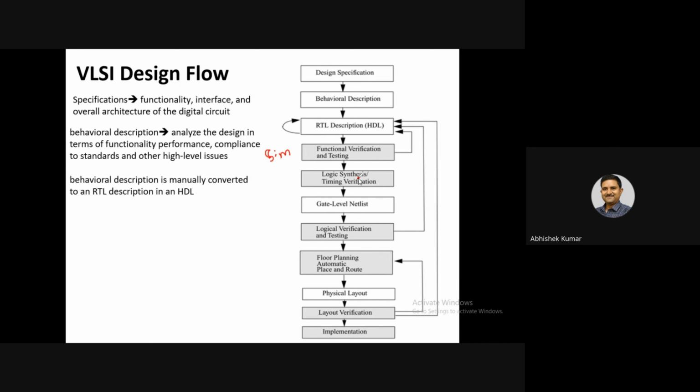Okay. So that is called simulation. Then synthesis. In synthesis, we ensure that whatever we have used in the program, in the operators or keywords, must have equivalent hardware. After that, again we do the simulation, which is called logical verification. That is functional verification or logical verification with the netlisted circuit. If there are certain bugs or unsatisfactory results, again we need to correct them in this step only, that is, by changing the program.